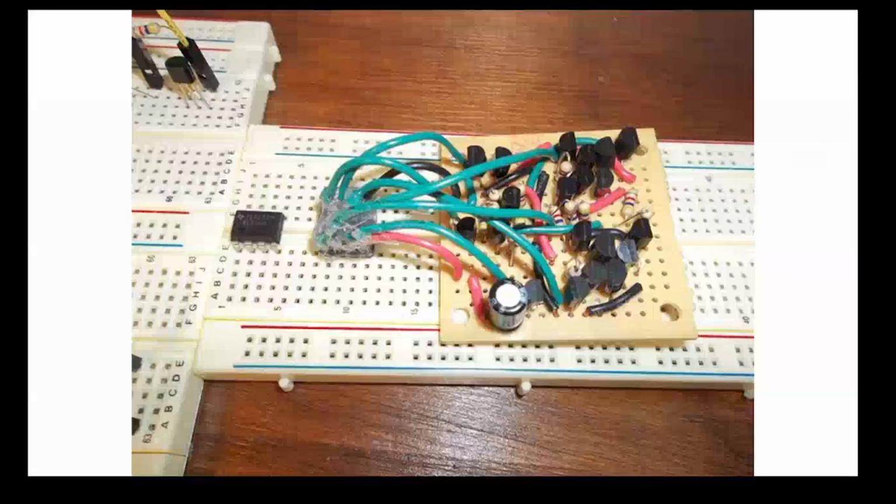But on an IC, if the frequency is also not that large, you need not worry about the matching. After the LNA, you can directly make the mixer without ensuring the 50 ohm match.